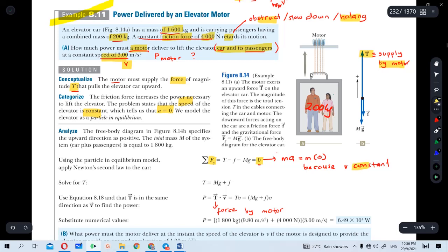And what are the forces? Number one, tension upward, minus friction, minus the whole weight that it has to bear, and equivalent to 0. Therefore, arranging the value of T becomes weight of everything plus the friction. Meaning, the tension has to support both. So according to this expression.